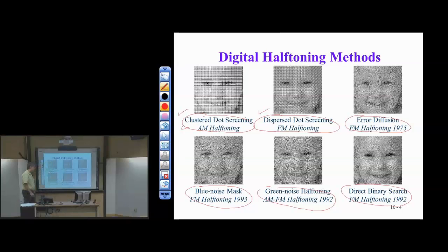It also swaps bits, but it does this in a way to try to drive down an error function to 0. And an error function is the perceptual distance between the halftone and the original. So they pass each image through a model of the human visual system, an LTI model, and then compare it basically as a mean squared error on the difference. And this is iterative, and it may take many minutes to get an image, versus a matter of milliseconds to get an error diffused image. All right, so it's more complicated, but it gives you an idea of what's the best you can do.